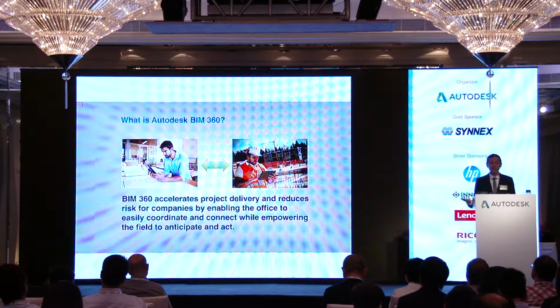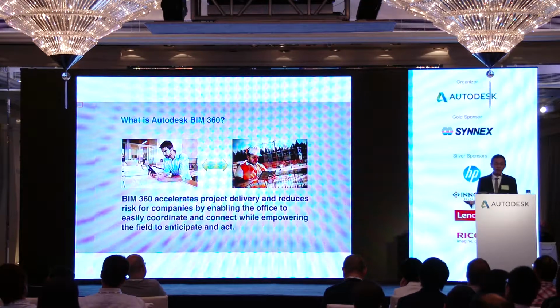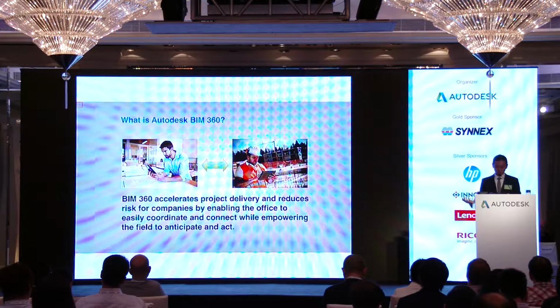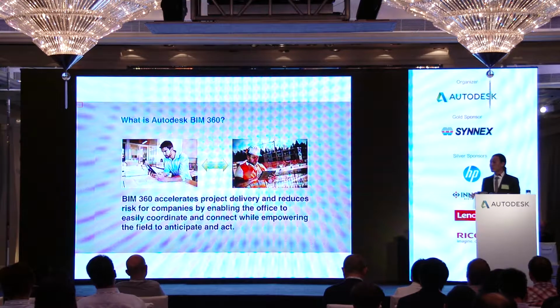And that's how I see it. The clash report in Navisworks doesn't work. It's all in green and red. Who the hell knows? It's over 10,000 clashes. Who could have time to look at 10,000 clashes? Solve the critical ones and leave the minor ones to be solved internally by engineers. And it's definitely less conflict within the BIM meeting or any sort of coordination meetings.